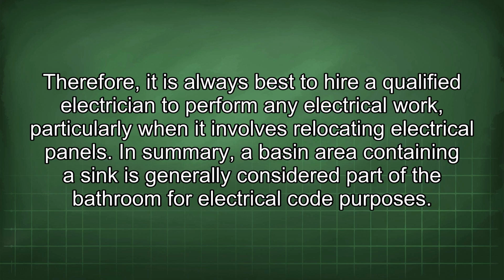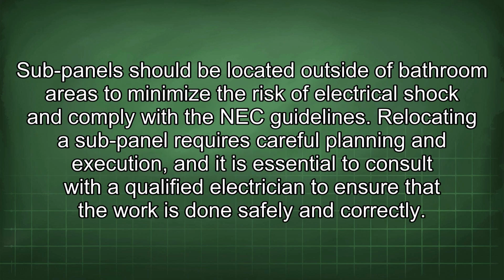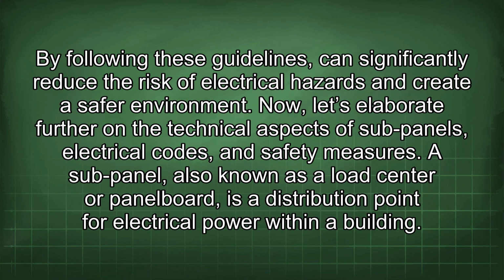electrical panels. In summary, a basin area containing a sink is generally considered part of the bathroom for electrical code purposes. Sub-panels should be located outside of bathroom areas to minimize the risk of electrical shock and comply with the NEC guidelines. Relocating a sub-panel requires careful planning and execution, and it is essential to consult with a qualified electrician to ensure that the work is done safely and correctly. Following these guidelines can significantly reduce the risk of electrical hazards and create a safer environment.